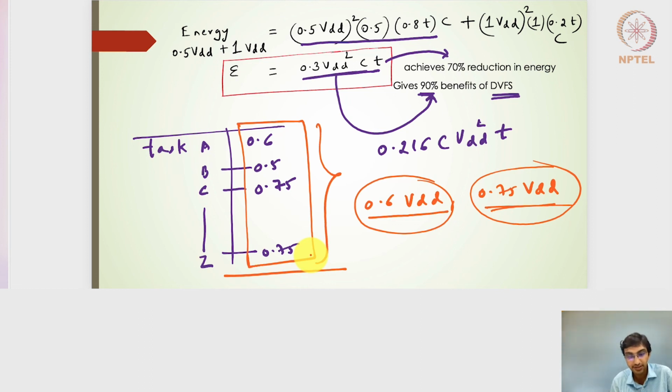So what we have learned in this lecture is dynamic voltage frequency scaling. What it really implies is, if we change the rate to complete a particular task, then the rail voltage should also be changed so as to get maximum energy benefits. But having many different values of VDD is not possible in a large higher-order digital design, because we will not have multiple rail voltages. What we will have are specific rail voltages, and that is where the tiered DVFS technique is very, very useful, which also gives us benefits very close to those of the natural DVFS technique.